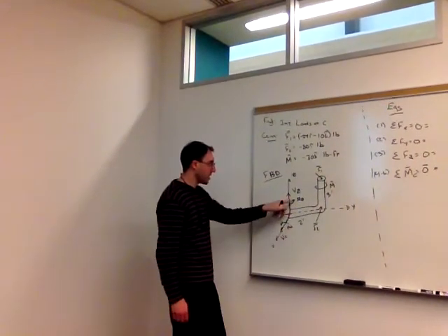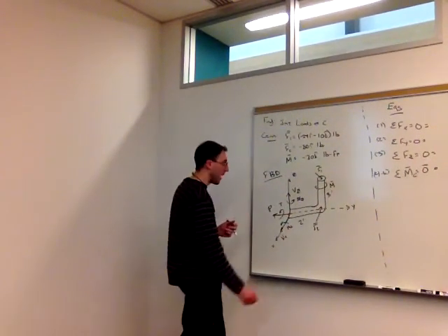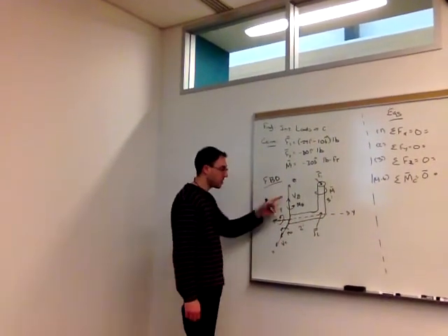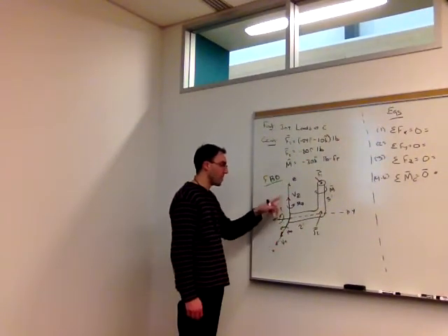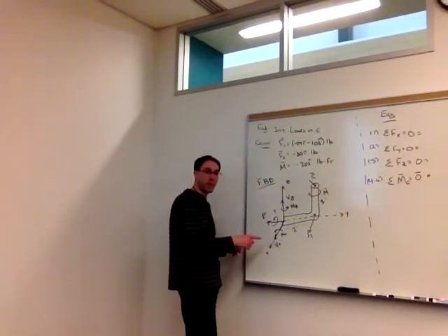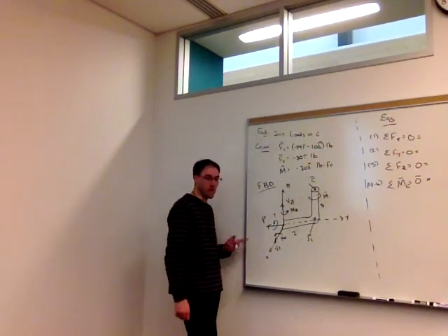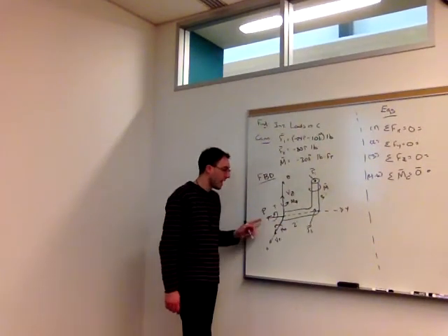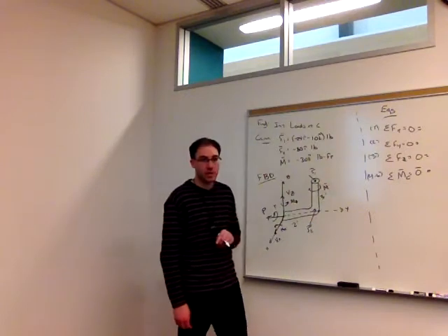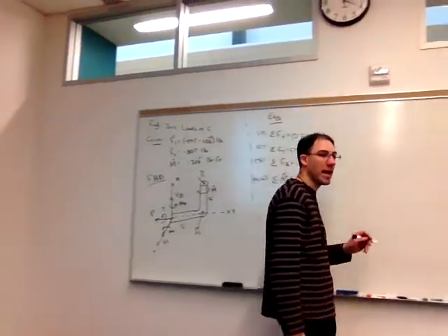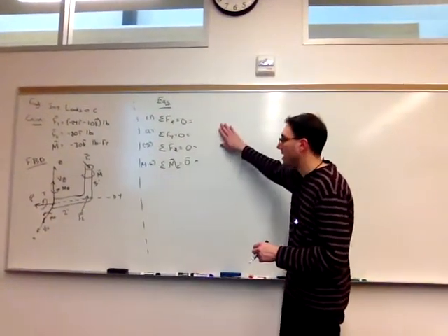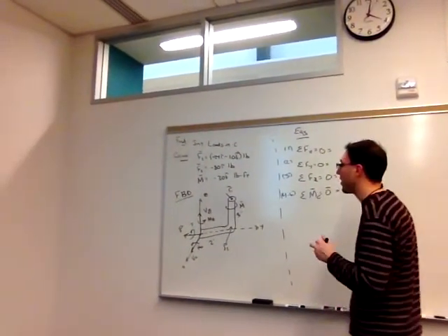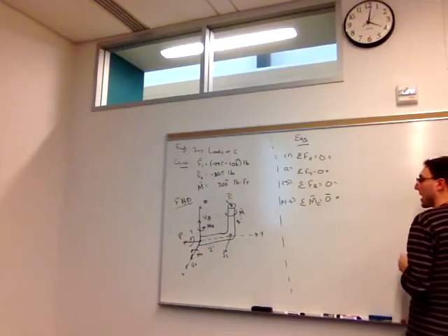And I'm going to assume that the bending moment components are also positive around the z and positive around the x-axis. So VZ, MZ, VX, MX are all around the positive axes, which we chose. P and T are around the negative y-axis as a consequence of the surface of the cut that we took. Using that free body diagram, then, we can go and write our equilibrium equations. So continue there, if you haven't already, to find the sum of forces x, y, and z.